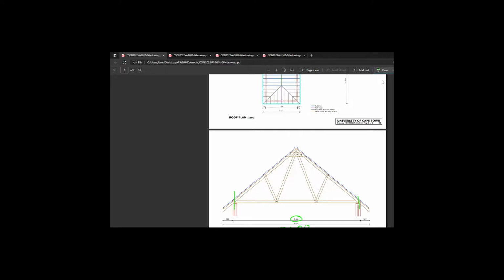I know it's confusing to understand. So you've gone from the outer edge and you're going 1 brick thickness inwards, and that is it. So we've subtracted 2 times 110, and you will get to 380. Okay, that's where that measurement comes from. So we are saying that the tie beam covers the inside span plus the brick and the cavity. Okay, brick and cavity on both sides. And if you're going from the outside, it's only 1 brick in and 1 brick in, and that's it.